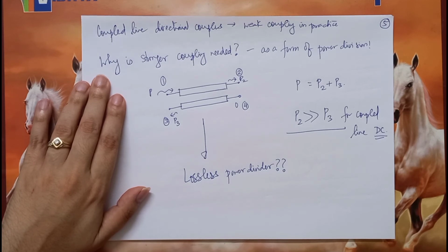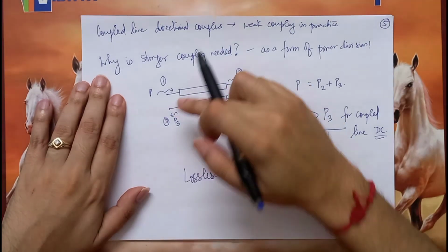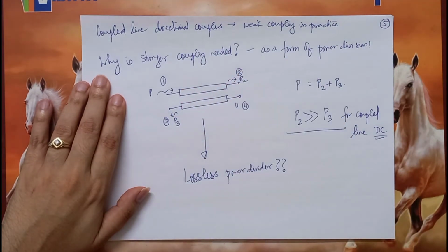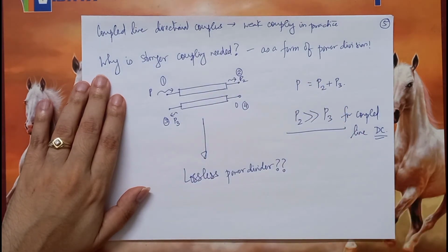That is, we are losing the right to call this a coupler. If we are giving direct paths between the two conductors, then there is no question of coupling. There is no question of any electromagnetic induction happening, because now the paths are there. We don't need to induce current in the second conductor. So those kinds of devices which have direct connections between the two conductors are not called couplers usually. They are called hybrids.